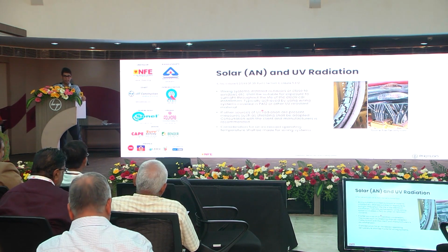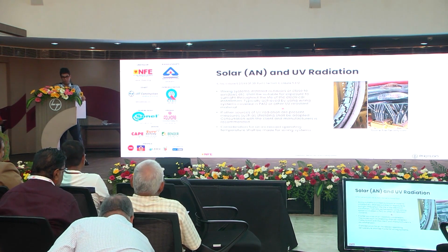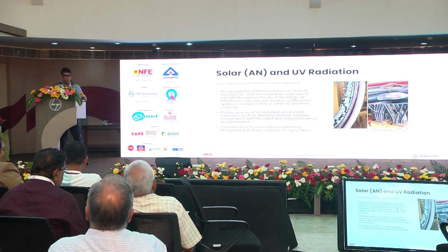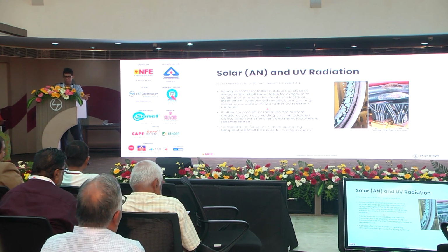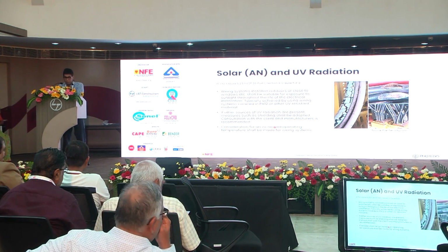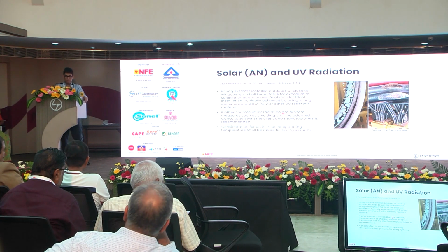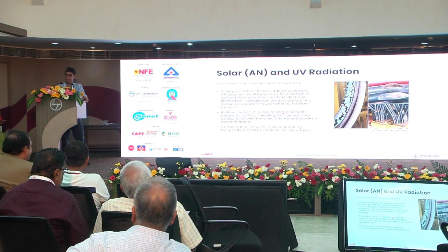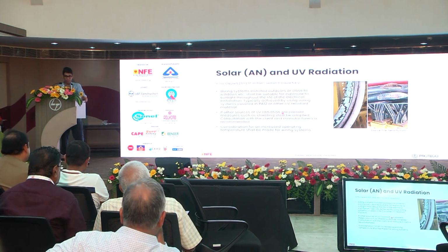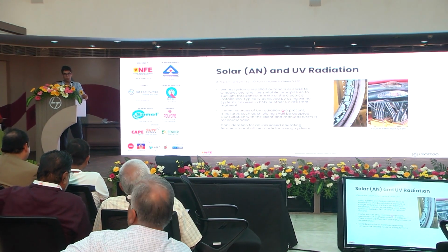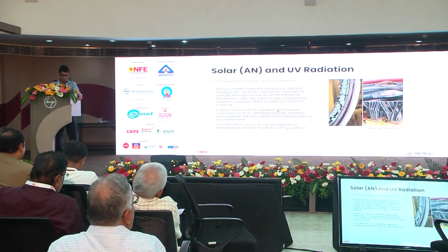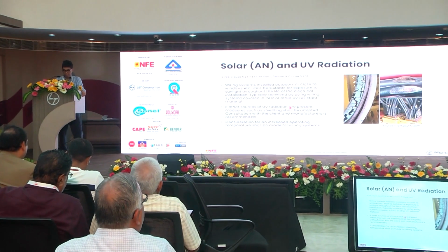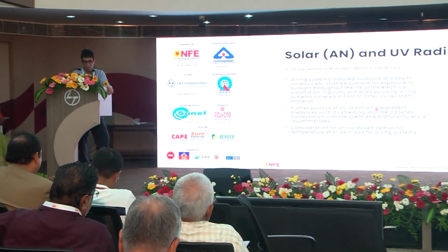Usually materials like PA12 are tested for a certain amount of UV resistance, especially for sunlight. Just use cables that are covered in PA12 or conduit that is covered in PA12. Manufacturers that make this are there. I'm sure Polycab also has UV resistant cables. Now, if there are other sources of UV radiation that pertain to particular manufacturing processes, then shielding or other measures are required, and obviously you will need to consult with the client and manufacturer. That is outside the scope of IS 732 and SP30.